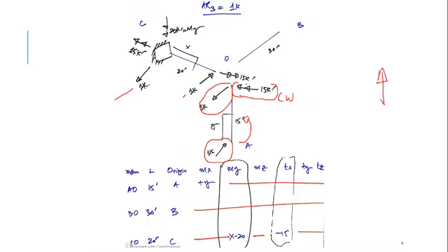You should know that this is anti-clockwise in y. This is anti-clockwise in z. This is anti-clockwise in x. Counter clockwise or anti-clockwise, it means this is clockwise. I have balanced this 15 kip foot with an equal and opposite moment, 15 kip foot, and this moment would be transferred to the point C, because this support can take this 15 kip foot.